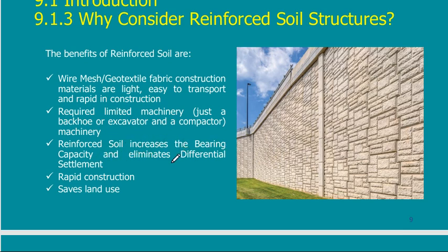Reinforced soil increases the bearing capacity and eliminates differential settlement. Of course, this is a very elastic wall. So it is not possible for this wall to crack or to deform, because it can carry any differential settlement from the soil. And finally, when I finish construction, if any settlement happens in between, I can just add more layers on top and I end up having a very leveled surface for this wall.